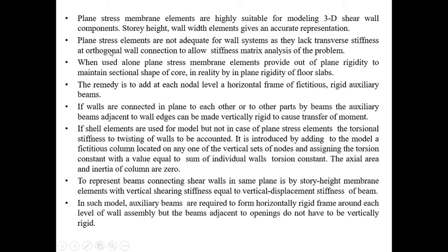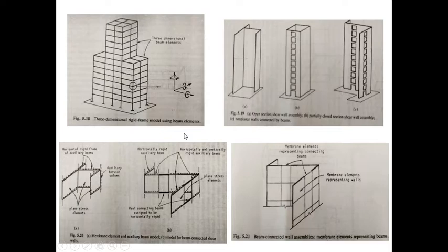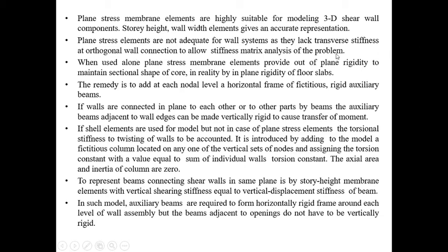Then the plane stress elements are not suitable for the wall systems. When we define them, they are not suitable for wall elements, as they lack the transverse stiffness provided at the orthogonal wall connection. At this orthogonal wall connection, this transverse stiffness will be lacking, and that will affect the stiffness matrix analysis of the problem.